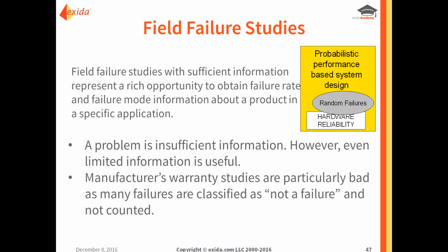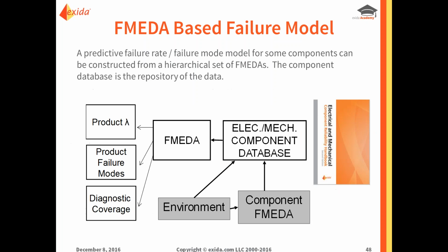But one of the problems with field failure studies is that sometimes manufacturers' warranty departments say, well, this isn't a failure, it doesn't count. Well, sometimes it could be counted as a dangerous failure. Even with a company with multiple locations, one team could say, well, this is a failure, and the next team could say, no, that should not have been counted. That's within the same company, let alone from company to company. So if you get failure rates from these types of applications and try to compare them, it's certainly not going to be an apples to apples comparison.